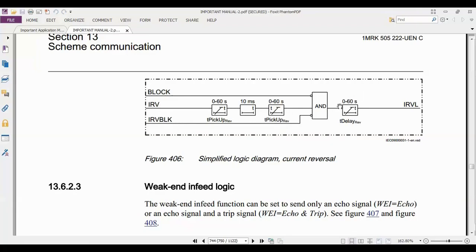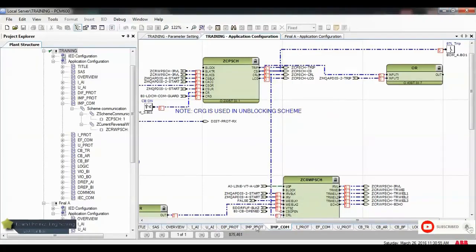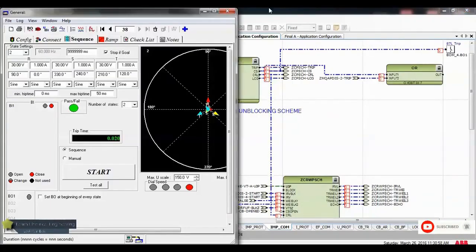Even if it sees zone 2, it still... So if it sees zone 2, it will just remain off with the off delay time. The time of the off delay is 100, and 100 becomes 200. Originally 200, how much does it become? It becomes 400. As soon as it sees zone 2, it gives you this part, and it starts counting this time of its own. Okay? Excellent. All right, I'm done here. Now I come to my injection part.